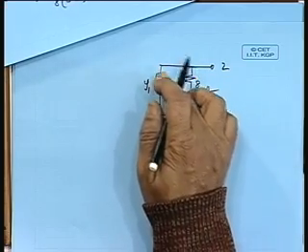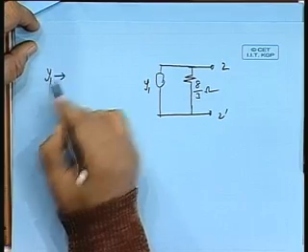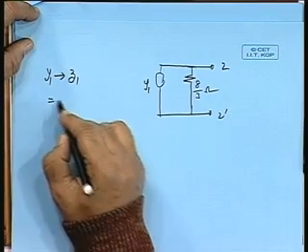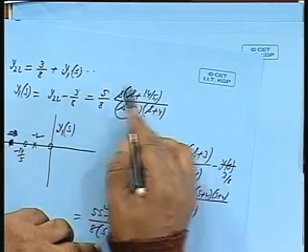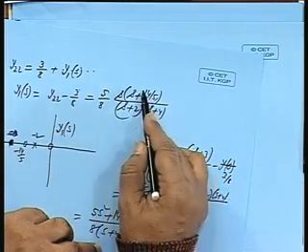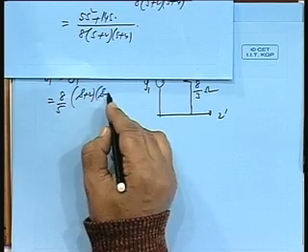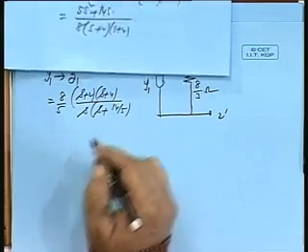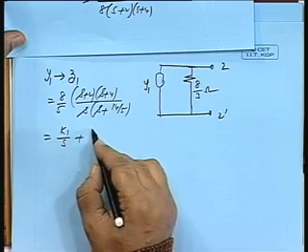Now, we have seen that there is a 0 at the origin. So, from y1 we go to a corresponding z1 because we want to realize that 0. So, what will be the corresponding z1? After removal of that constant, this was our y1. So, the corresponding z1 will be 8 by 5 into s plus 2 into s plus 4 by s into s plus 14 by 5. Okay. So, remove this as k1 by s plus whatever is left over, I call it z2.